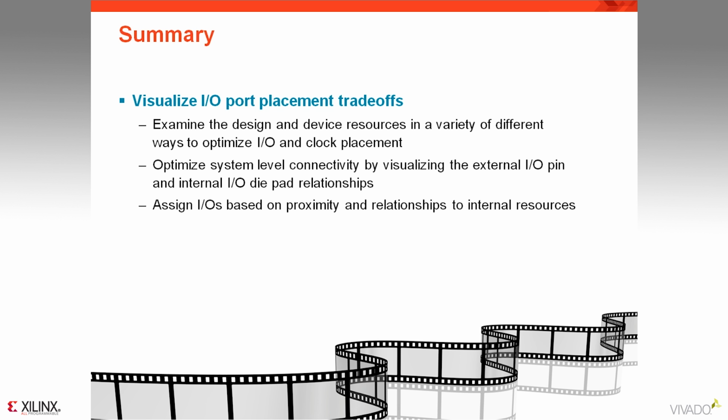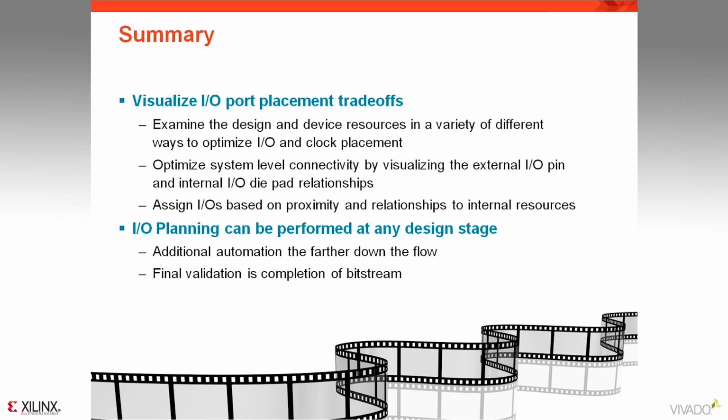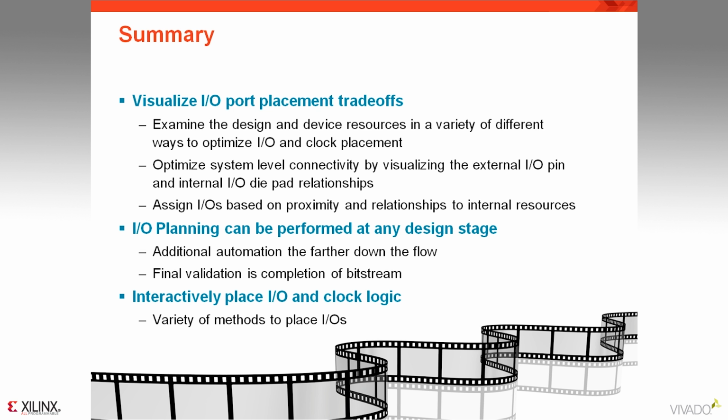I/O planning can be performed at various design stages, including prior to having RTL, after RTL, and after synthesis. The farther down the flow, the more automated design rule checks and interactive design capabilities are made available. There are also a variety of interactive placement and validation capabilities built into the environment.